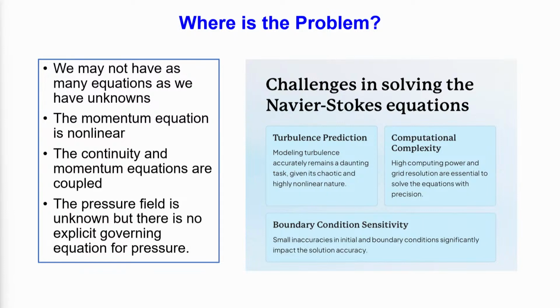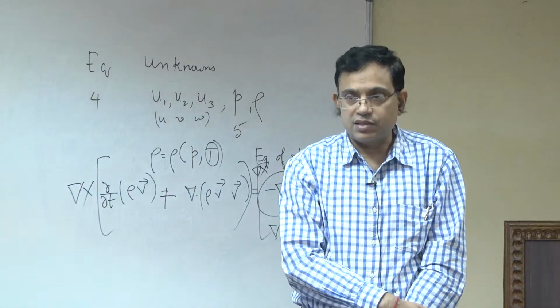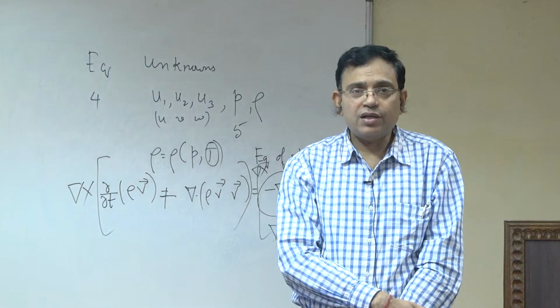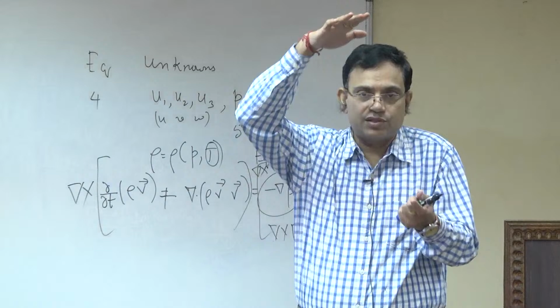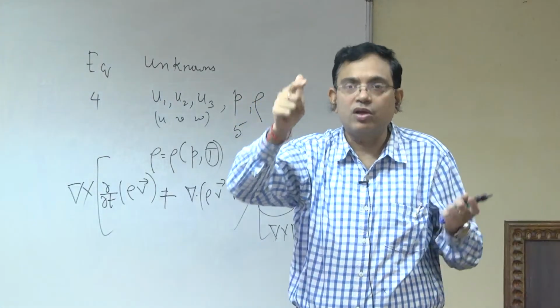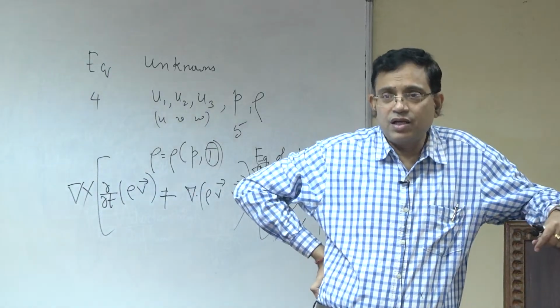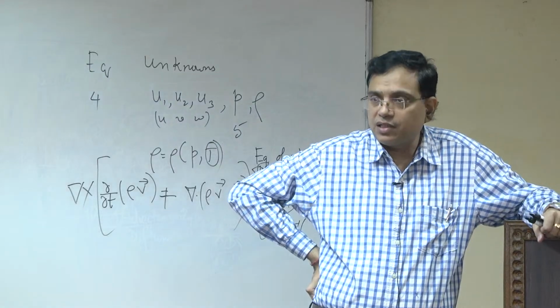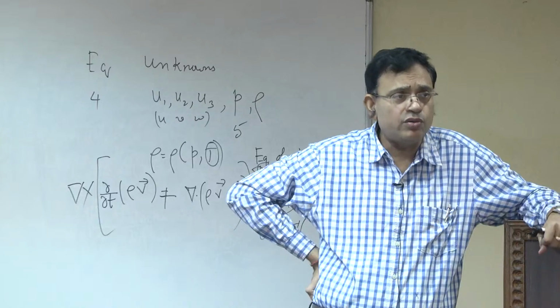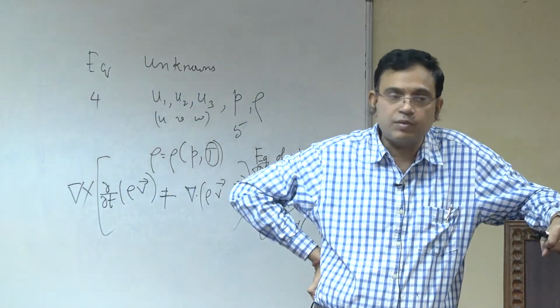You also have other challenges which I am not explicitly telling, say a turbulent flow. If you have a turbulent flow, you have at least got a feel that to solve a physical problem you need a time discretization and space discretization. For a turbulent flow you have a wide range of time scales and a wide range of length scales. So, the resolution has to be really fine, where you are trying to capture the physics from the large eddy, which is of the channel size, to the smallest one, which is of molecular dimension. So, it is not straightforward to do. Although in principle you may apply the Navier-Stokes equation, it will go to such a huge computation that only for a selected class of problems, with very high performance computing power available, can you do it. That is known as DNS, direct numerical simulation of turbulent flow.